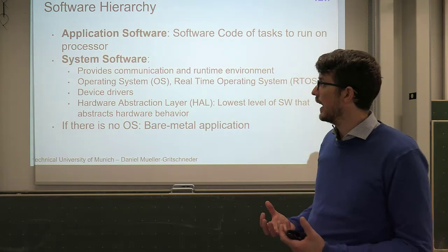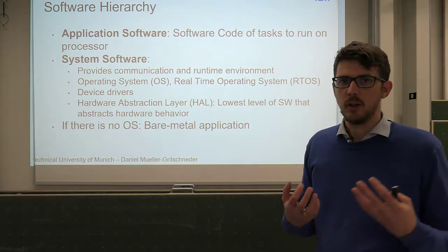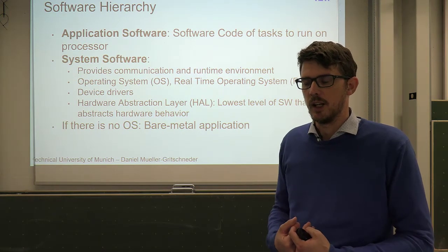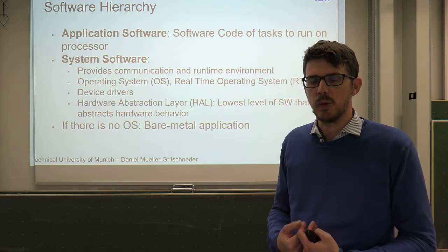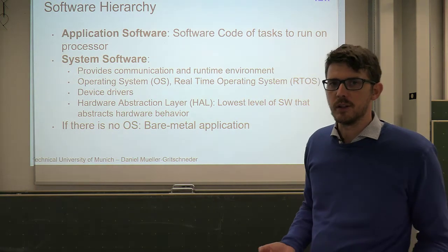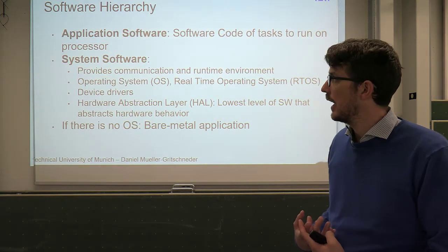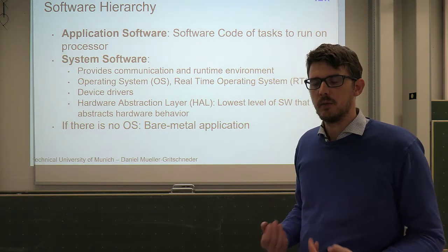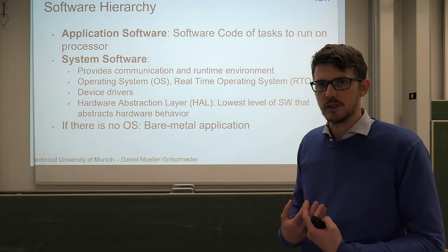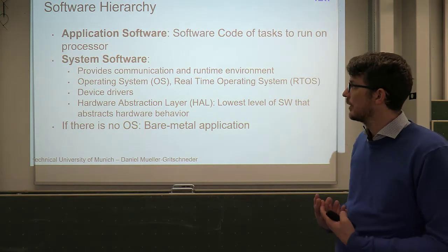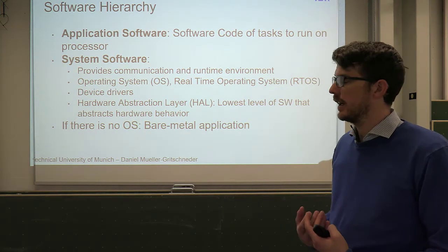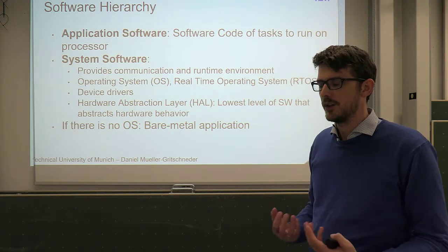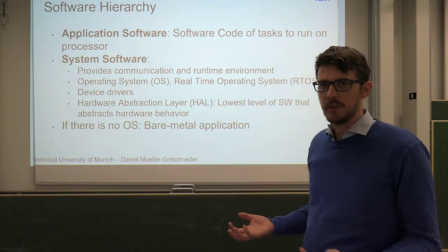So now how does this look? Usually you have your application software on top. That will be the software which does the sensor readout. It might do some processing of the sensor data, some reasoning, or it might be a control task, and these are the tasks you're running. This application software then runs on top of a system stack consisting of system software. This system software provides communication, so access to the hardware, and it also provides a runtime environment.